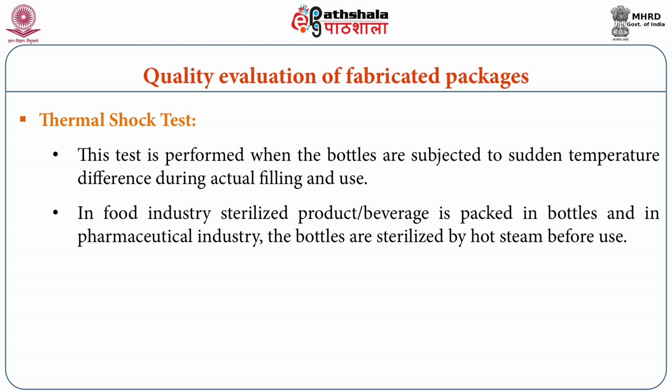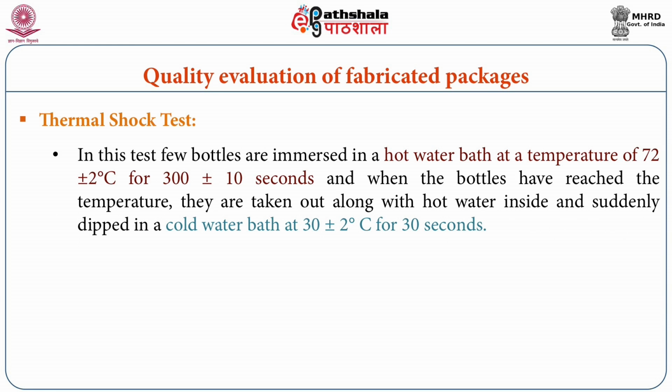steam before use. In this test, a few bottles are immersed in a hot water bath at temperature of 72 plus or minus 2 degree centigrade for 300 plus or minus 10 seconds, and when the bottles have reached the temperature, they are taken out along with hot water inside and suddenly dipped into a cold water bath at 30 plus or minus 2 degree centigrade for 30 seconds, and then the cracks developed are observed.